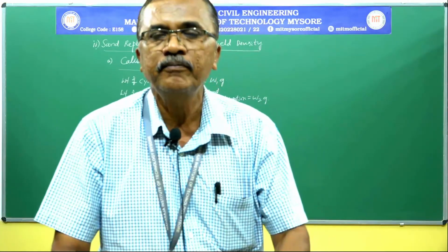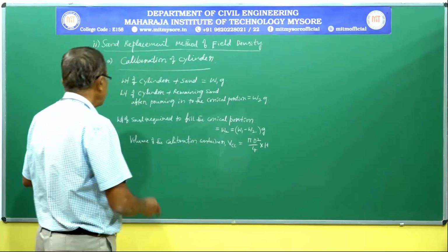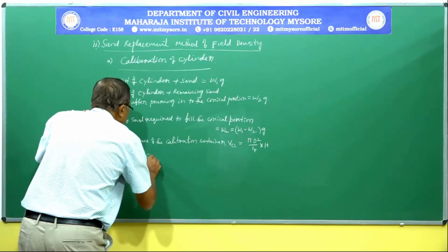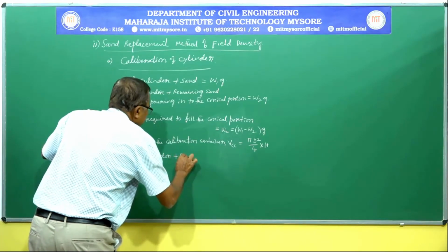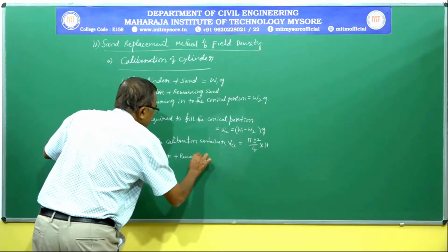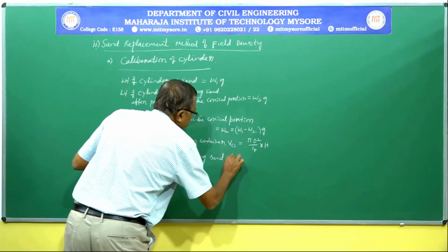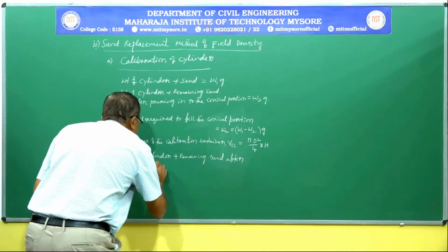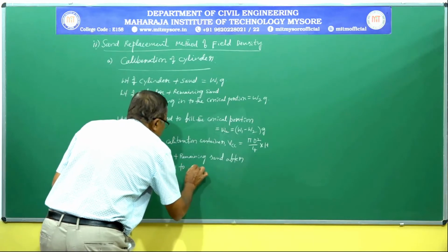Again note down the weight of cylinder plus remaining sand after pouring into calibration container.